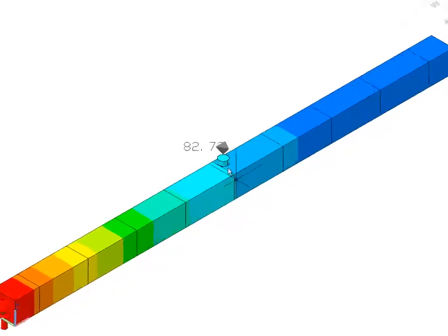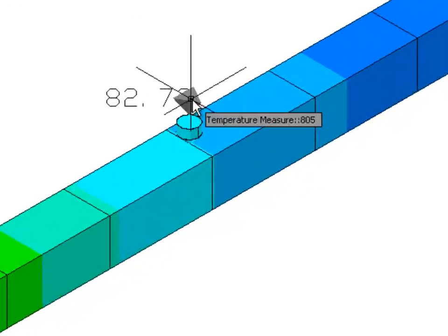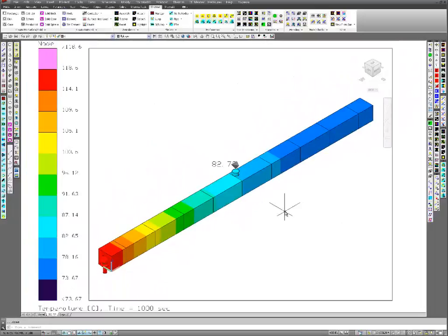The thermal node on the end here has not been updated since it was not present when that run was made. But if it had been, it would also be blue, and I would also be able to link it with a data logger. If I had changed the resolution of that bar, of course, the measure point would stay at the same location and interpolate between different nodes. But since I am fortunate enough to have a node at exactly the right place, I won't use a measure in this model.